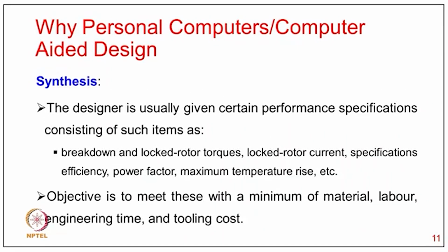Now the other approach to the design, which we call the synthesis approach for computer design of these single phase induction motors. The designer is usually given certain performance specifications consisting of such items as breakdown or locked rotor torque, locked rotor current, specifications like efficiency, power factor and maximum temperature rise, etc. And the objective is to meet these with a minimum of material, labor, engineering time and tooling cost.